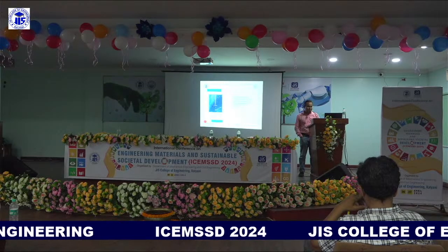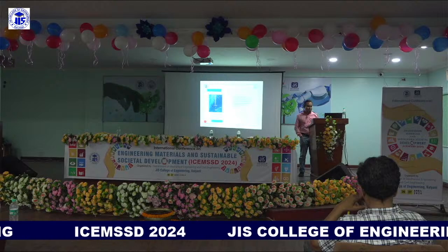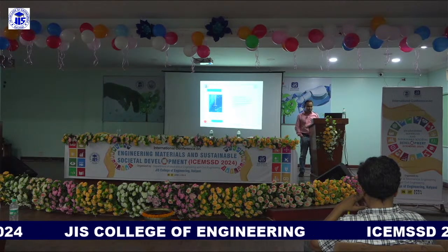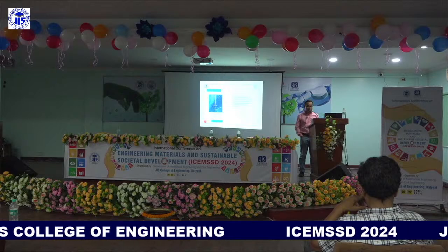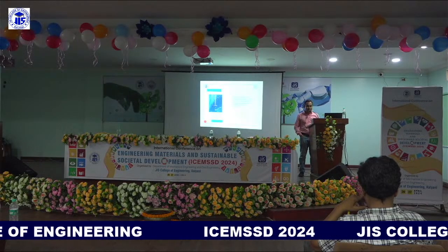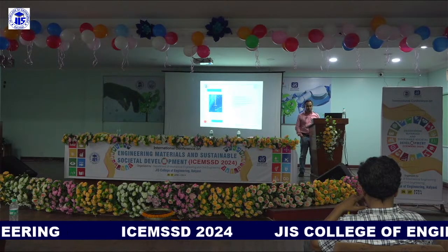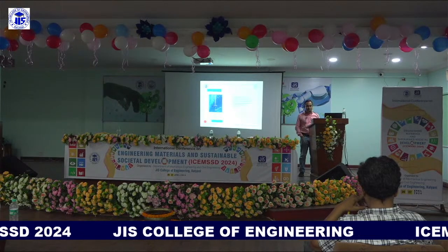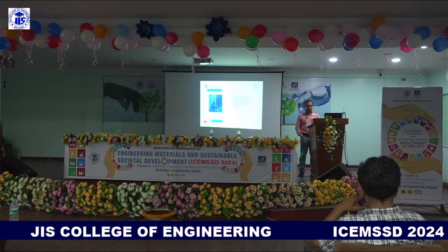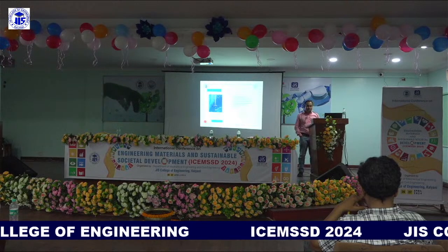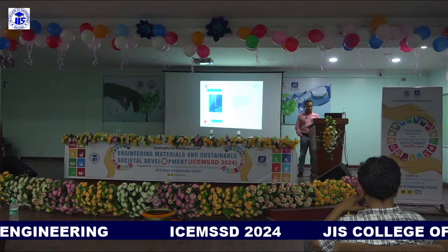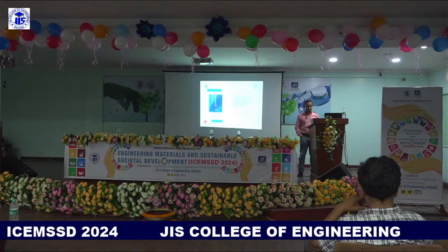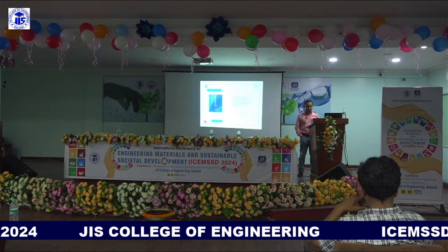Here are the details of the instrument by which we capture the velocity readings. It is called the Vectrino, and it has four probes which are able to give velocity readings in three different directions, and with this we get 100 velocity readings in three directions every second.